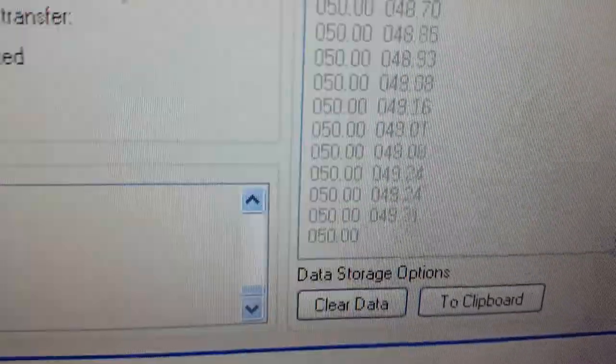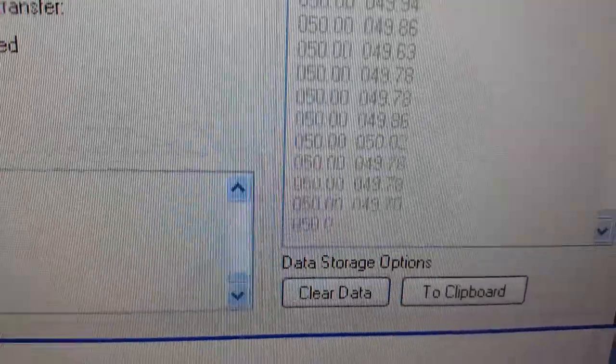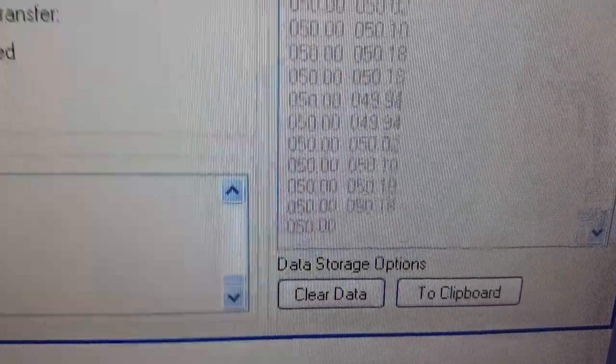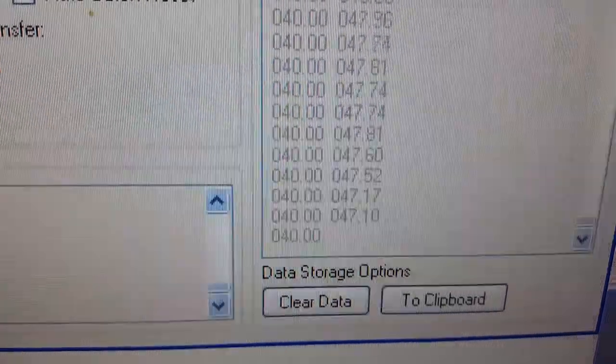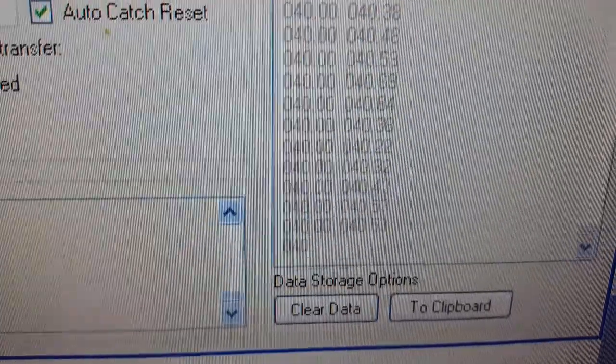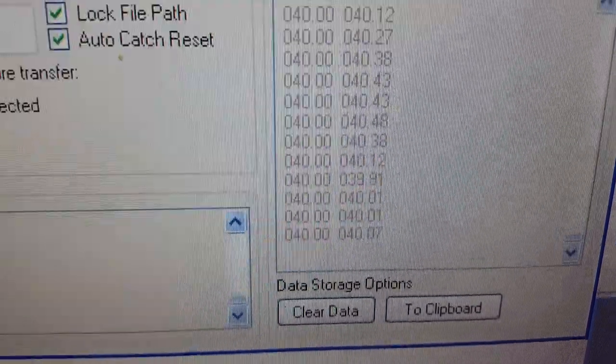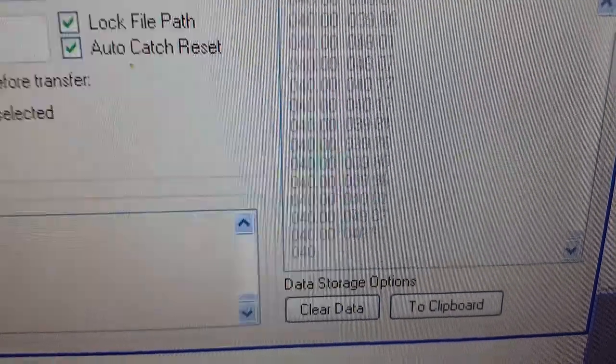And here, I modified the code so I can change the set point from 50 to 40. When the set point is 50, the left column, the actual speed goes to 50. When I change the set point to 40, the motor slows down. You can see that in the right column. And eventually it goes to 40 radians per second. For type 1 systems, there's no steady state error for step input.